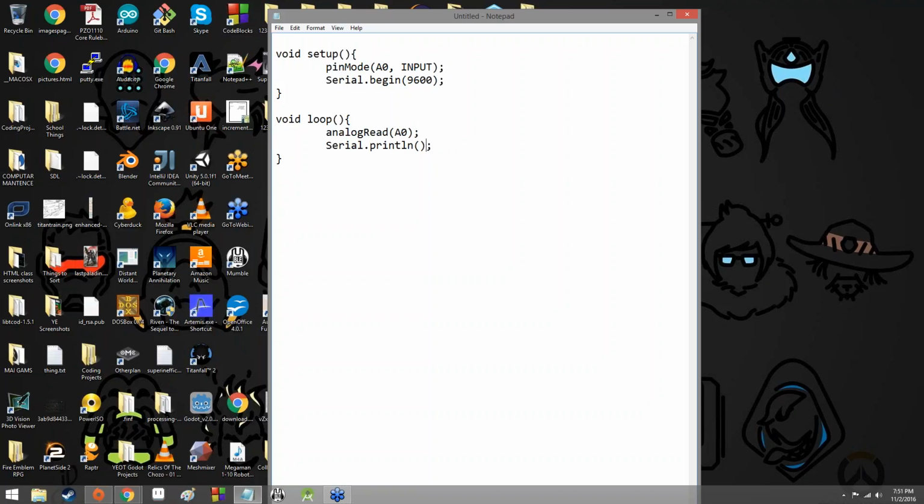All right, so yes, Serial.println, but what do we print? Well, we can do this. We can say int LDR equals analogRead(A0). So right now, we set up an integer variable called LDR, and we're setting it equal to whatever value is returned from analogRead of A0. And then Serial.println, we're just printing LDR, so we're printing out that variable value. Now, this would be good enough. Your Arduino would do exactly what you want it to do with this alone.